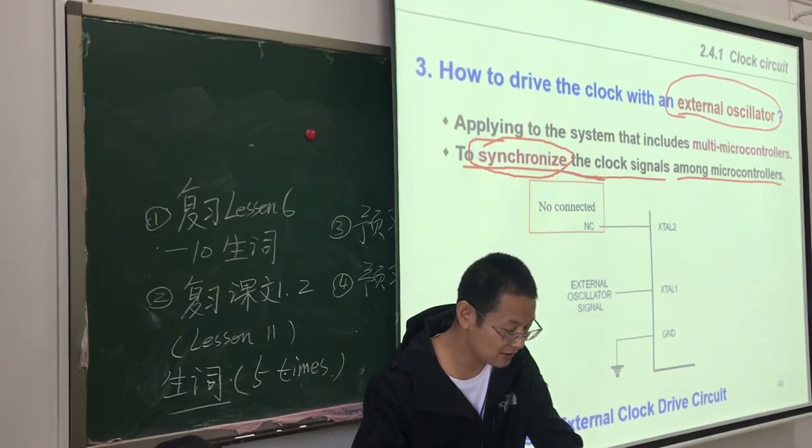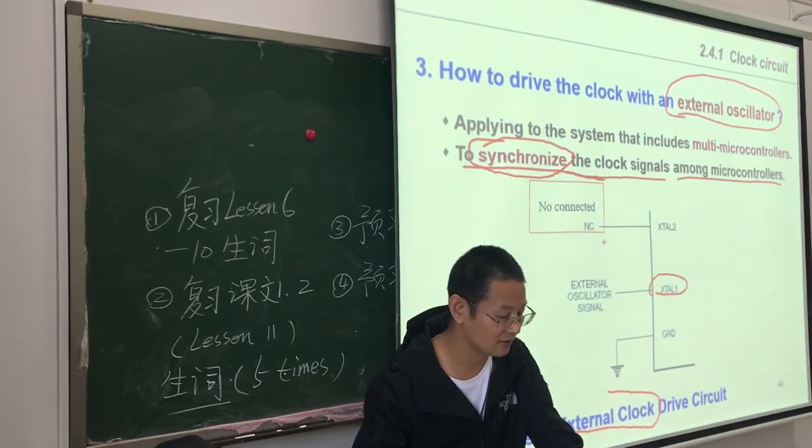For the external clock, the connection is simple. Just connect to XTAL1. XTAL2 is not connected.